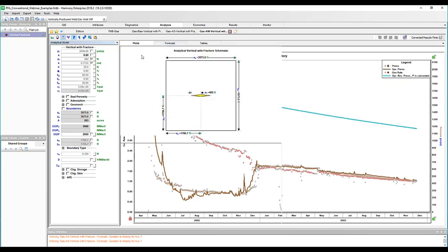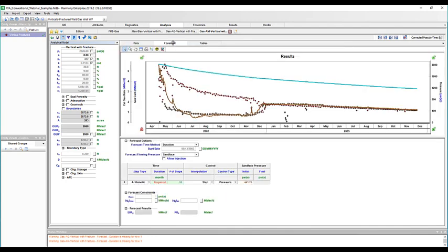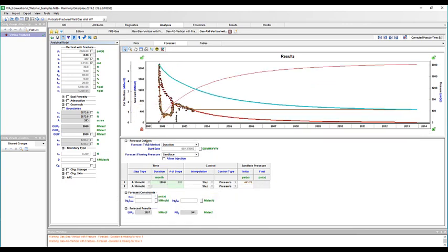So this has been used to look at the past. Now let's take a look at the same model to predict the future production using the Darcy's flow physics model. What we actually have is a forecast tab. So I can do, for example, a forecast of 10 years. And right away, we can see that we get a plot of our history here and our forecast on the future, which is based off of that reservoir model. And you can see that it generates your forecast results, such as your EUR and your remaining recoverable gas as well.